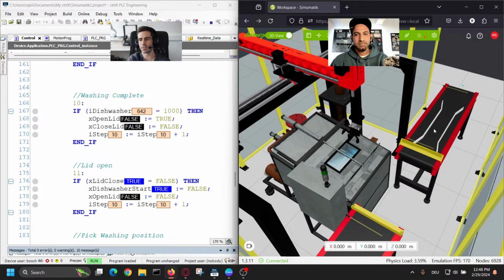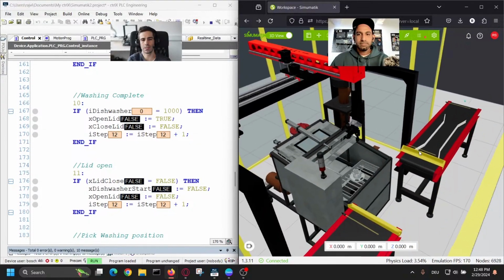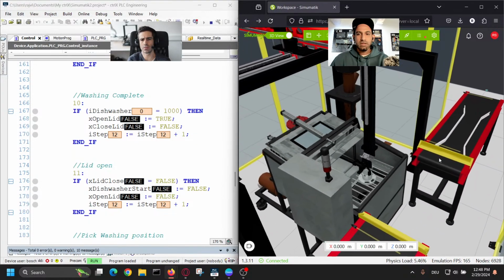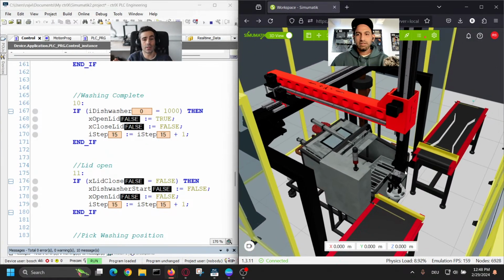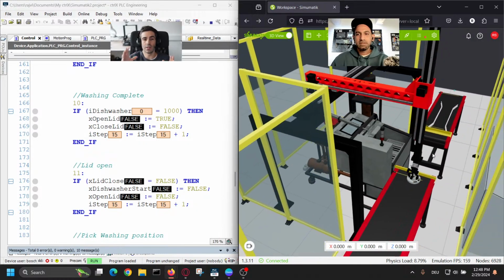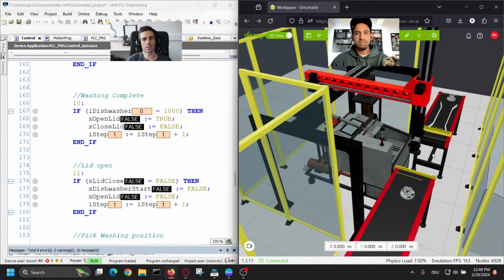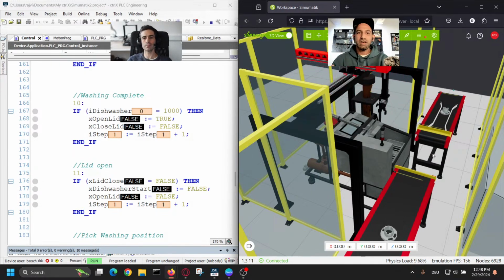If you want to run the ctrlX completely in software, do you need a virtual machine, or can you install it on your Windows PC as well? I mean, it's just software, and the web interface is completely the same. The apps interface is completely the same. It's just that you don't have hardware. It's just a soft PLC, just like a Codesys soft PLC as well. I shared it with Daniel. I think he would be playing around with that, and maybe he can also execute it.